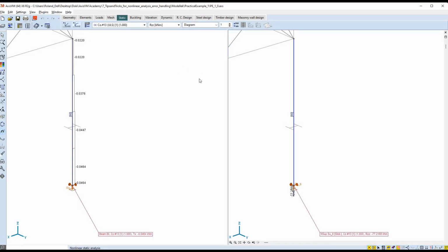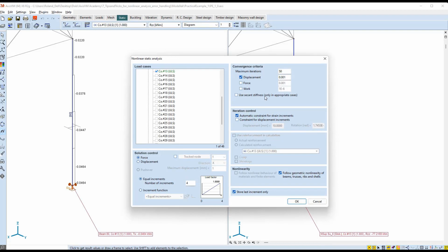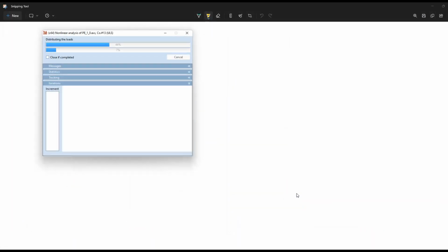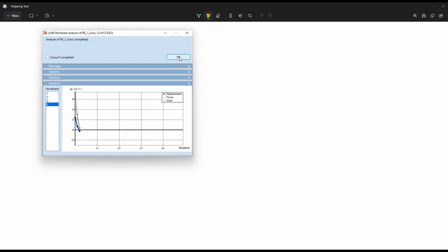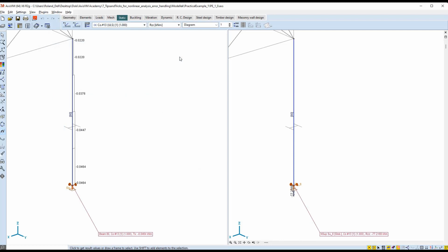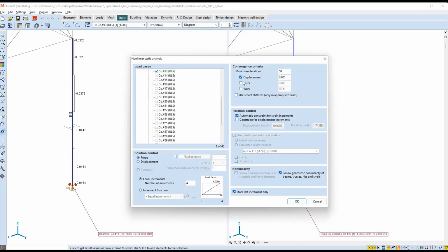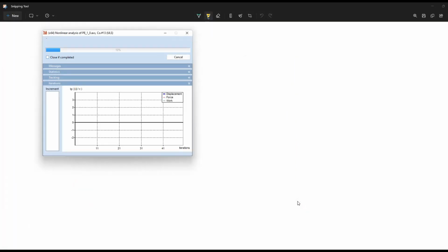As the first step of troubleshooting, we try to modify only the parameters of the nonlinear calculation. On one hand, it can be the easiest way to resolve the problem. On the other hand, if this trial is successful, the user doesn't have to change the model. At first, let's take a trial with 10 equal increments. It is the default value, and this is the minimum number of increments recommended if any problem occurs.